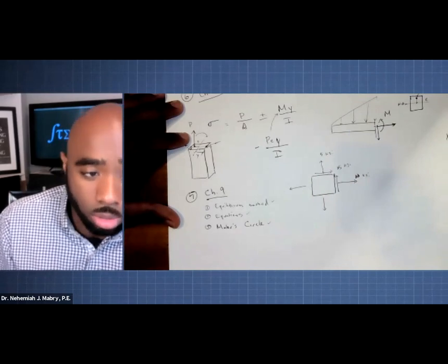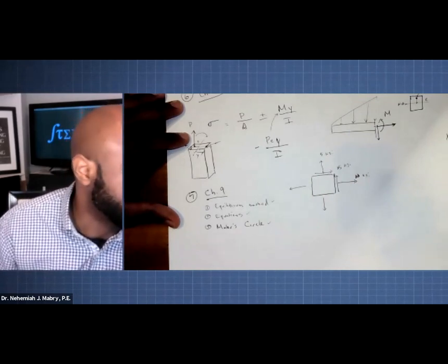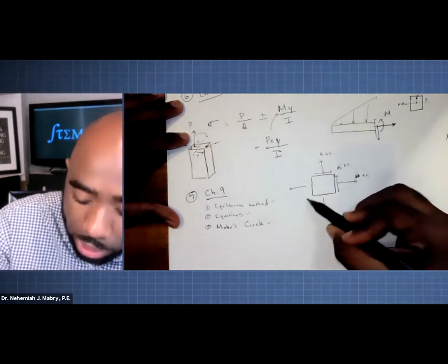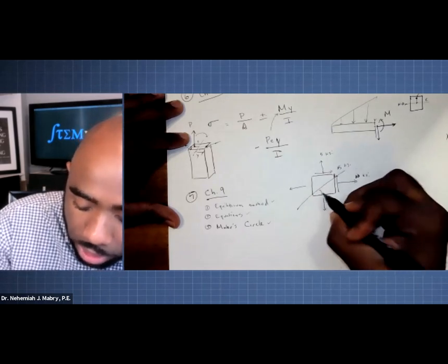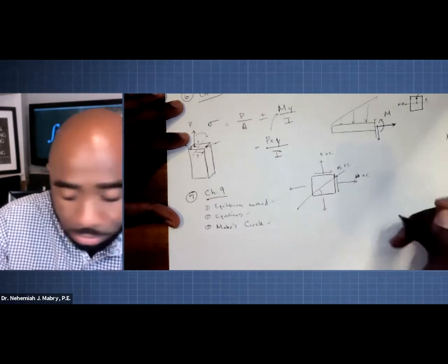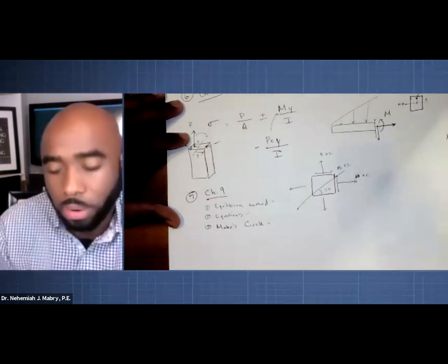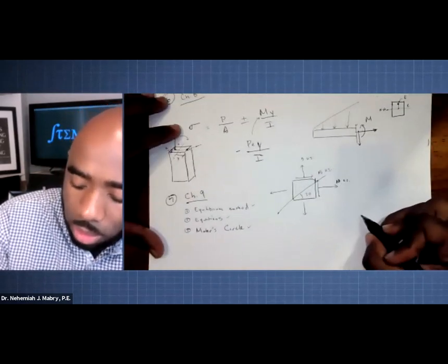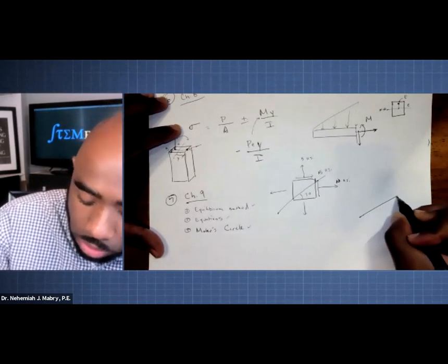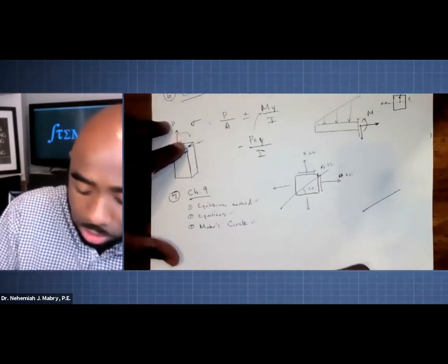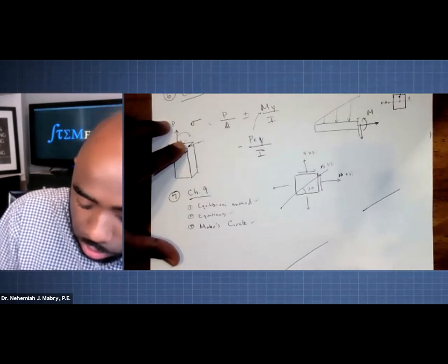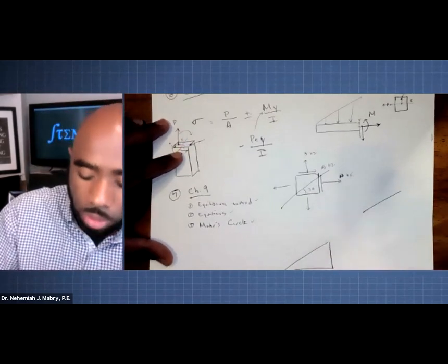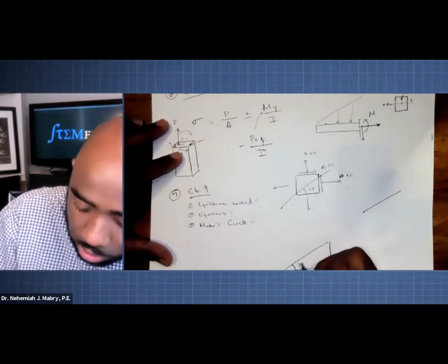But they're asking you to find the stress transformation, or the stress components acting on a certain inclined plane. And they give you an angle of, I'll just say, 30 degrees. All right. The way you would then go about solving this is now drawing your triangle. Matter of fact, I'm going to do it down here just so we can clearly see what's going on here. Draw that triangle representative of this rotation, 30 degrees.